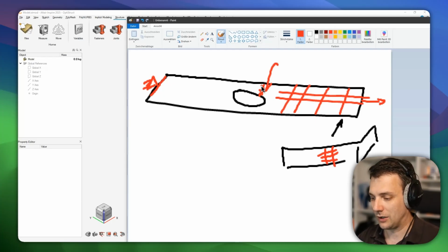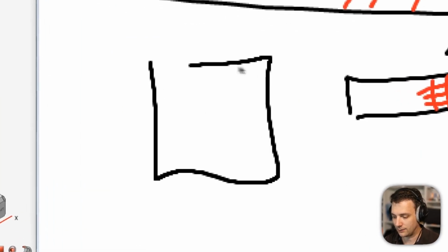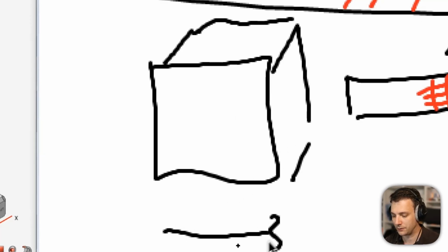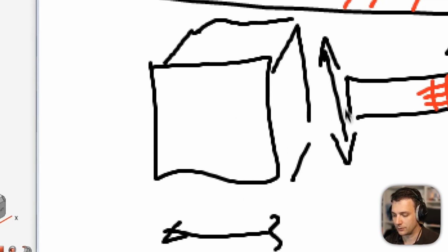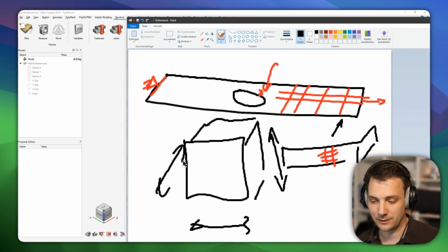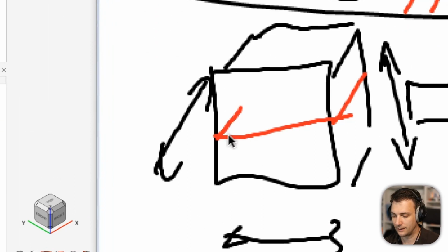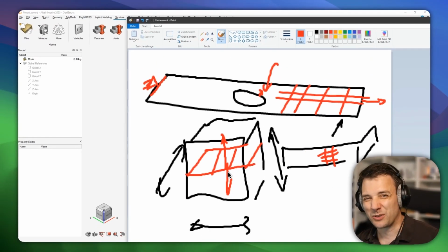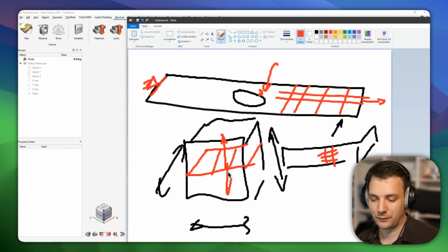It does not make sense to try to mesh a cube-sized object, where you have dimensions 1, 2, and 3 with similar sizes, with a 2D mesh. I mean, you could, right? You could extract a mid-surface, do elements there and assign a thickness, but it would not really be a good approximation of the real geometry.